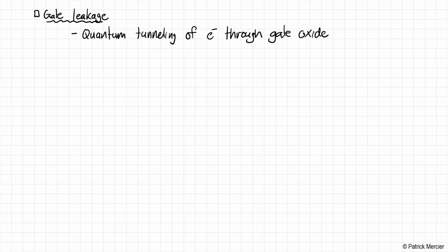In fact, I had some colleagues of mine who designed some chips in 90 nanometer, and they had a lot of extra silicon area available, and so they decided to make a large network of decoupling capacitors using MOS capacitors, basically using a MOSFET as a capacitor. This is normally a great idea. If you have extra area, decoupling always helps.